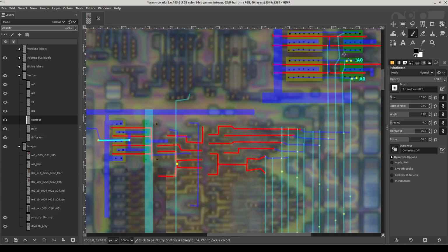So now if we follow these signals out from the address decoders, we can see that they jump down onto metal 1 for a short time and then onto poly, and they go into something here. And what we're probably looking at here is essentially a 5-input AND. And so we have one of these indicating that the corresponding address bit is in the correct state for this row to be activated. So if this is logical row 0, that means that we have address 0 is 0, address 1 is 0, address 2 is 0, address 3 is 0, address 4 is 0, and so on.